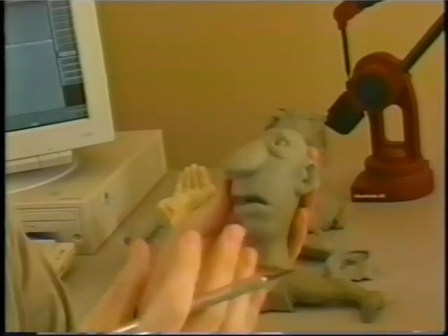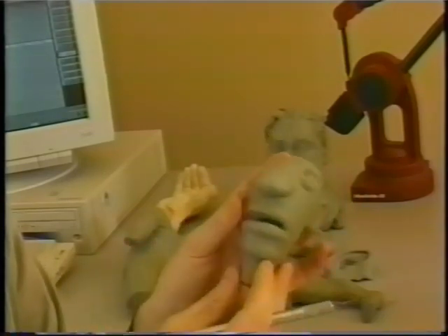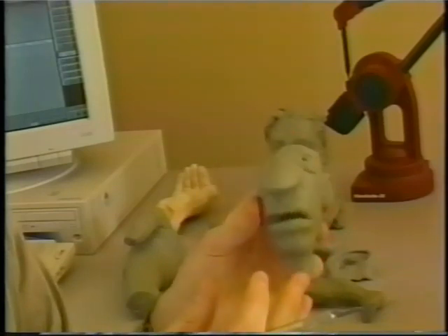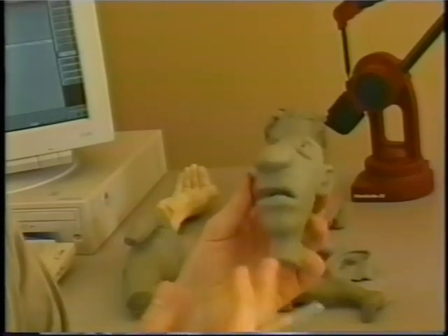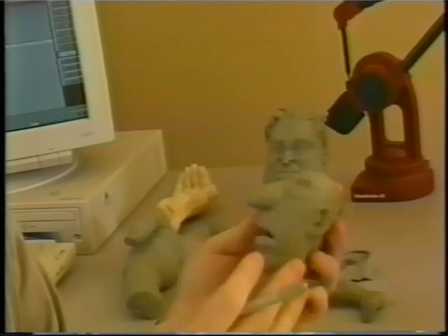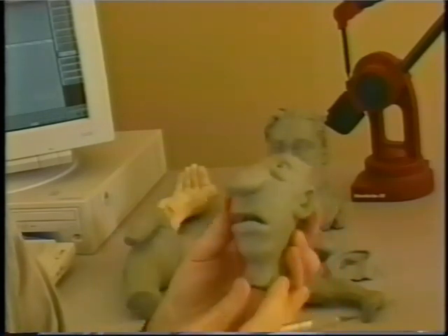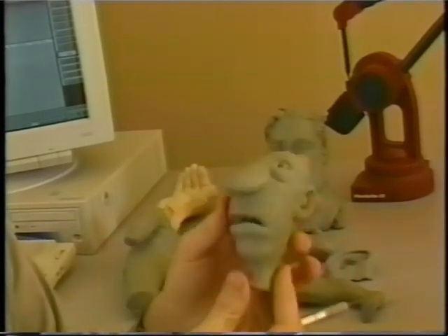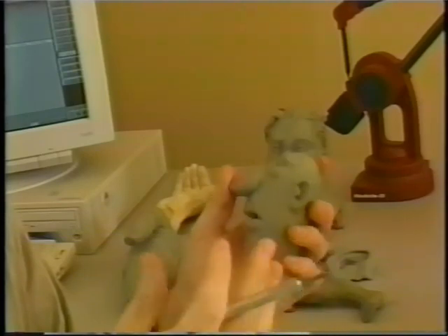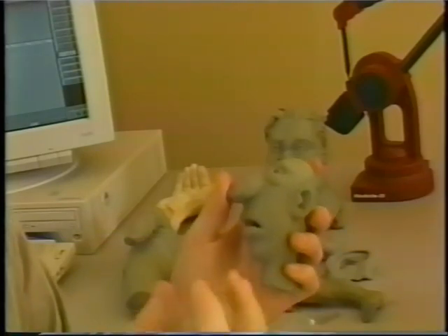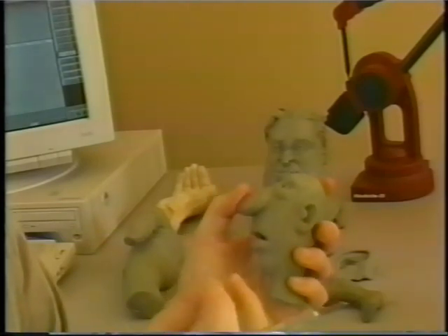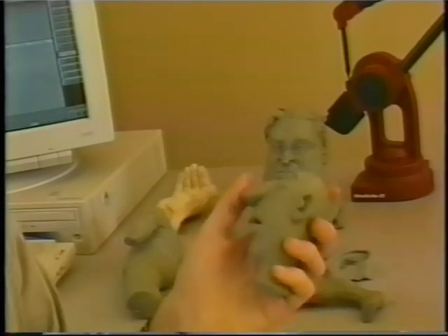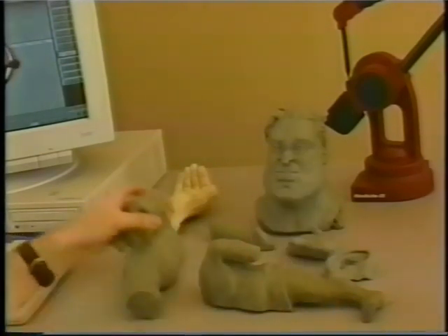And the opposing truth is that the more discrete NURBS surfaces you have, the more you have to resort to all these not so good connection techniques to get them together. This one wasn't hard, but some of the other ones are hard and don't always work perfectly. So you want to keep your NURBS surfaces as small and discrete as you can. On the other hand, remember, if you have too many, then it gets difficult as well.